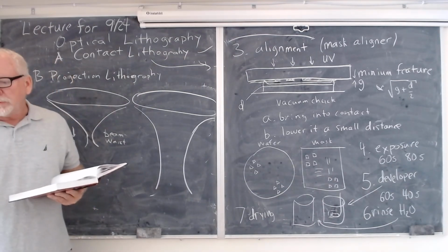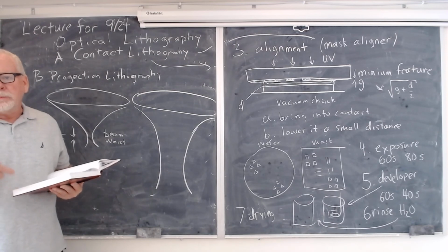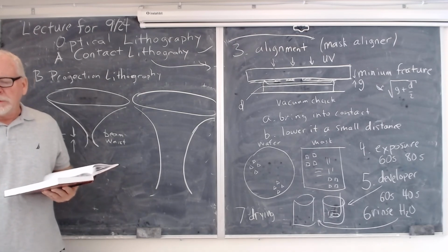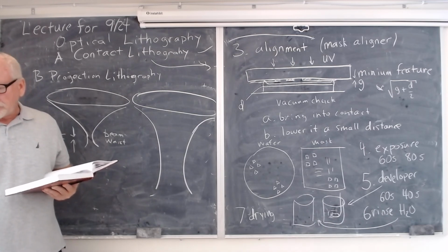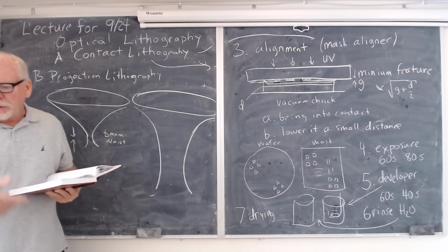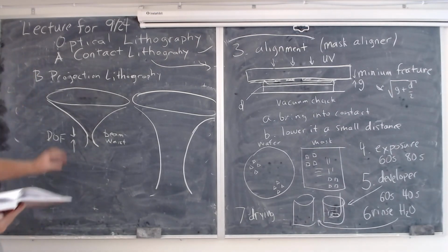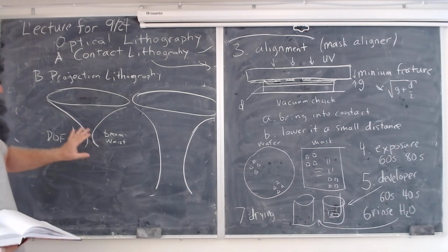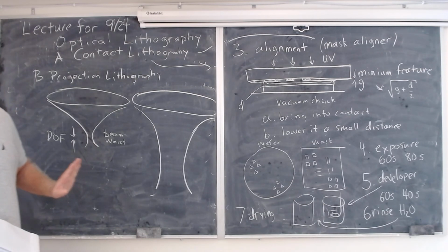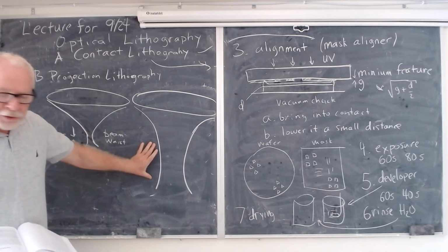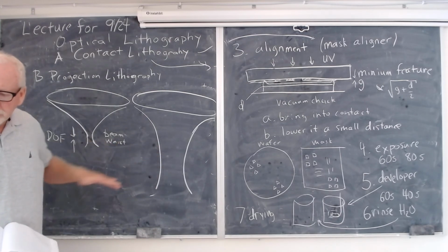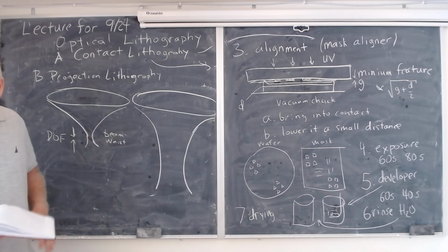Actual foundries are at the point where the topography and the wafer bowing itself, which is microns, impact the depth of focus, and so they have to do a trade-off between tighter focus and longer depth of focus because of imperfections in the topography and bowing of the wafer.